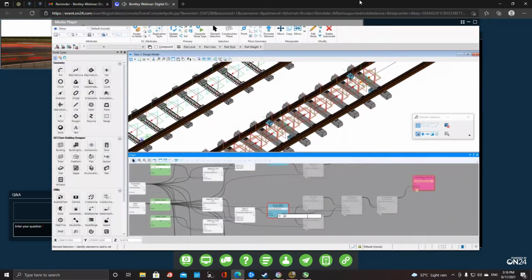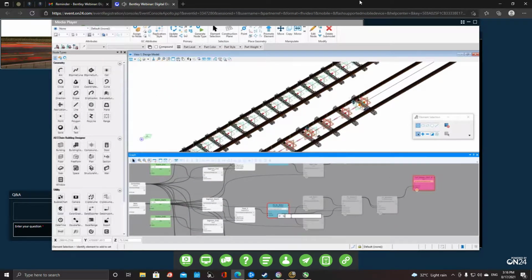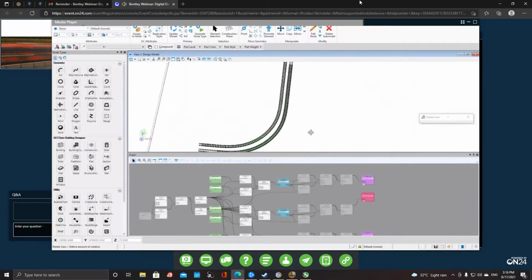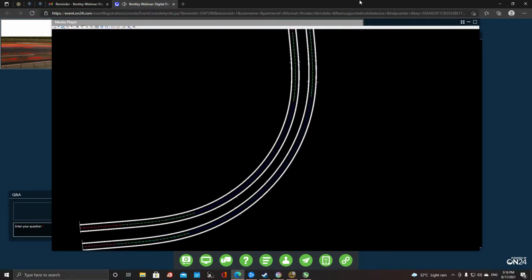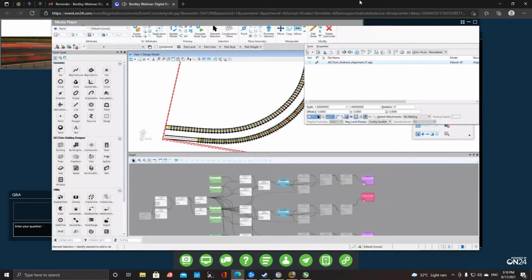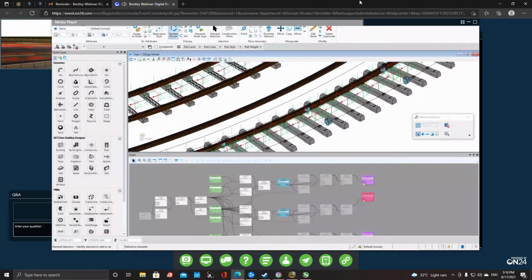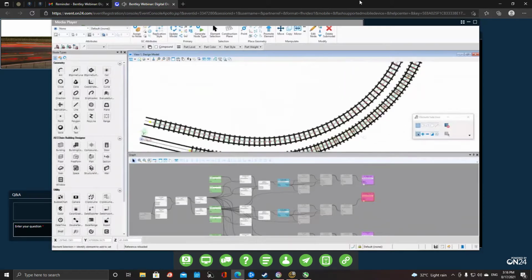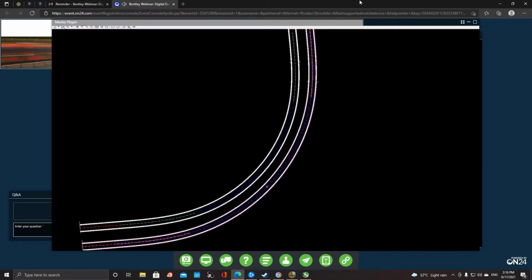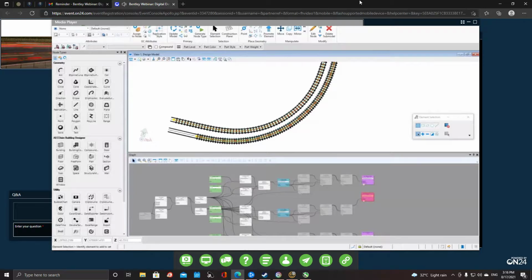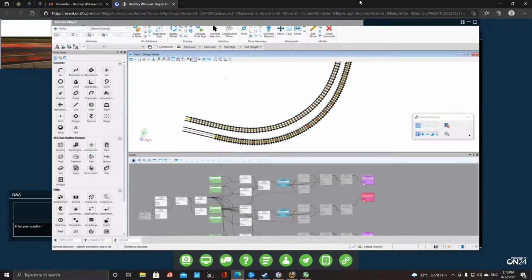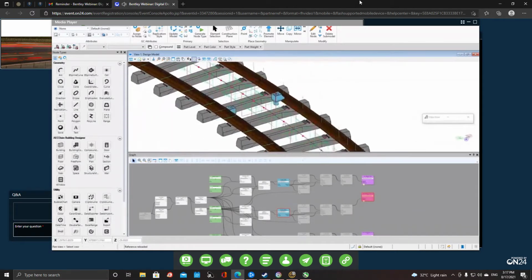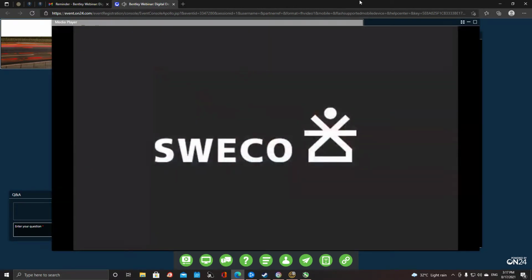This means we can have a computational scripting approach without all of the members of the team being able to script. The alignment engineer might make an amendment to the alignment. That is the civil engineering software, which can then be referenced into, in that case, EcoSim, which is now Open Building Designer. And we can then follow that same alignment with the script.